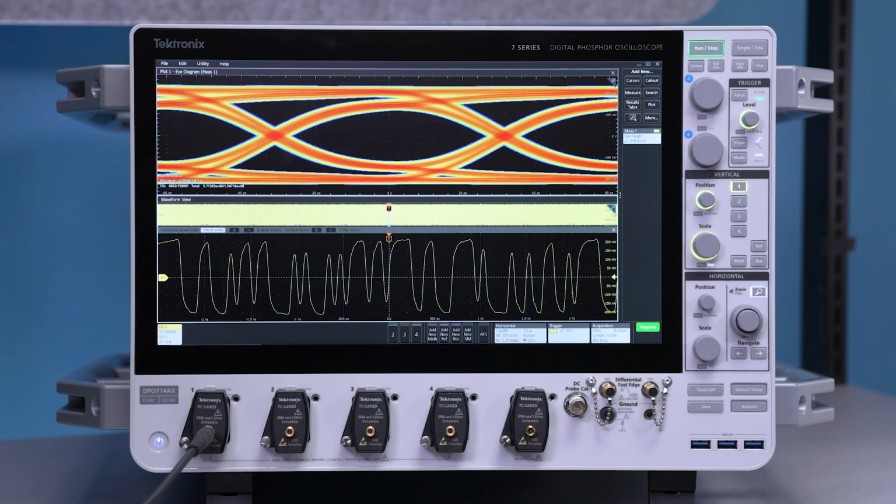Measurement accuracy can easily be enhanced by accessing the new SIM, or signal integrity modeling, which allows you to de-embed transmission line effects, view virtual test points when probing close to the device under test is not practical, or simulate extra components to better reflect the real world, effectively performing a simulation of your design under different conditions.